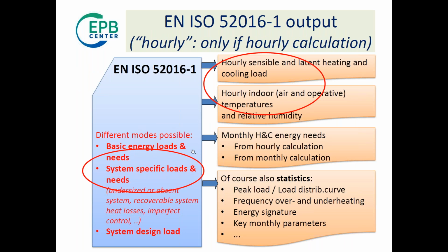Also shown at the previous webinar is the type of output of the 52016 part 1. And this time I concentrate on the calculation of system-specific loads and needs. That's the interaction with the systems. And the output is then the hourly heating and cooling load and the hourly indoor temperatures.